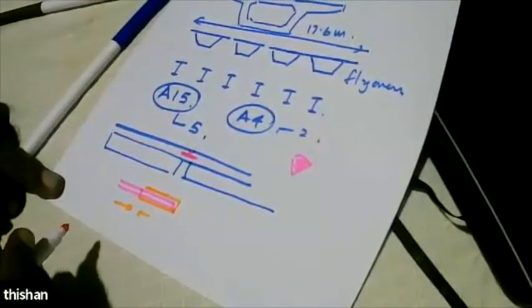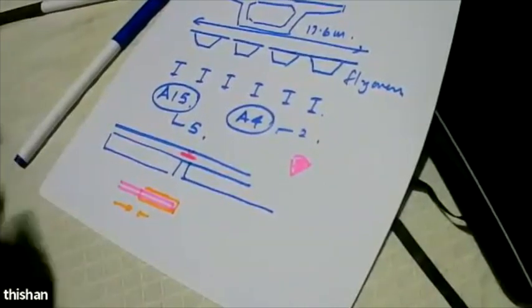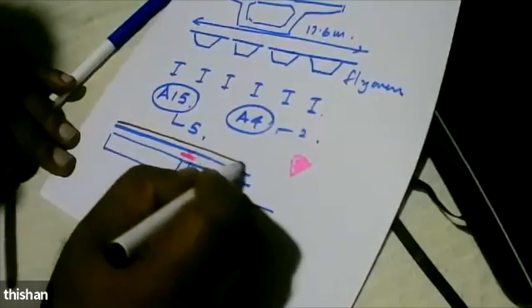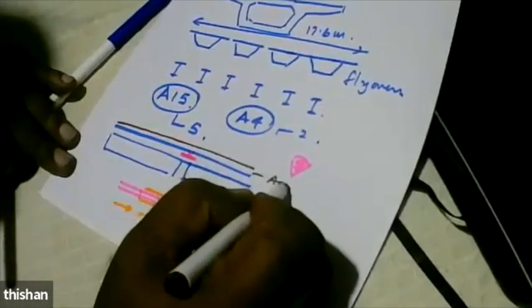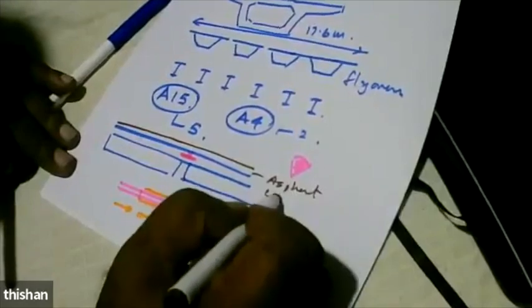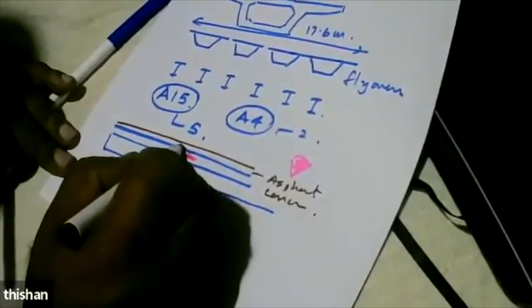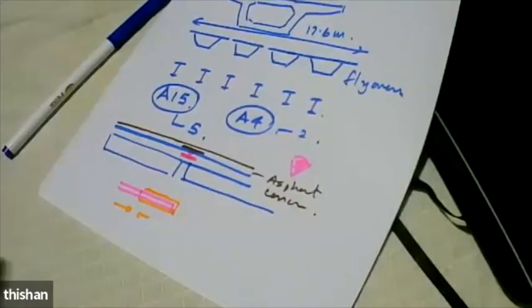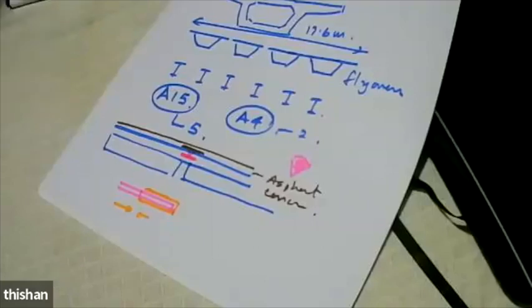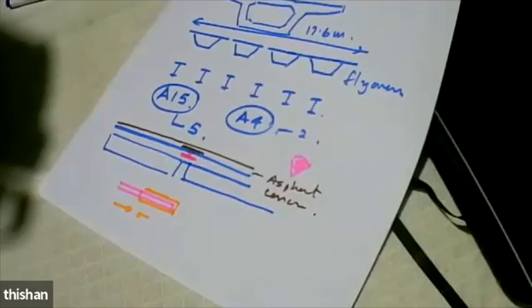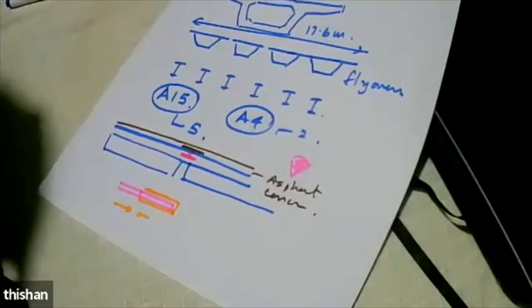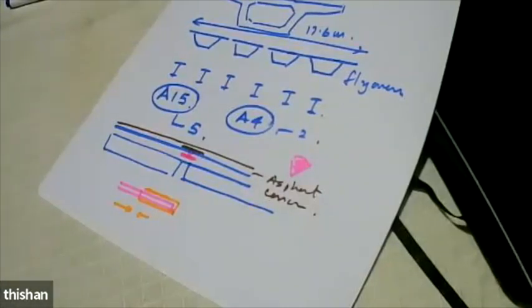So we use this particular joint, and then what we did was we laid concrete. And if you want, you can layer geotextile. So this was done, and it was very successful. No problem whatsoever. You can't see the expansion joint, because there is no expansion joint as such. It's only a kind of continuous joint.